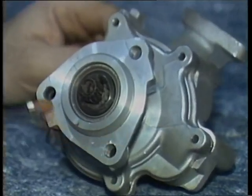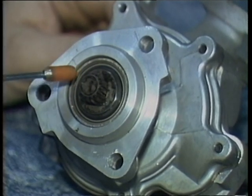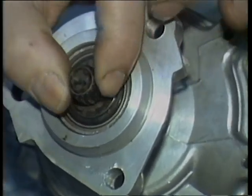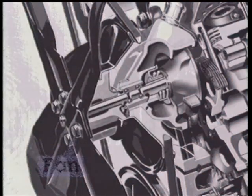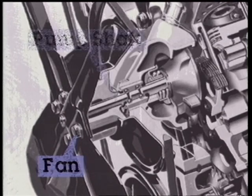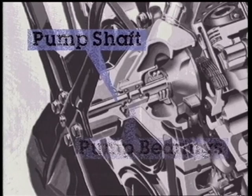This side-mounted water pump has a unique drive arrangement. It is a splined shaft that meshes into the rear of the drive gear. The timing chain on the engine, not a rubber belt, powers this pump. Here you can see how a fan typically bolts to the front of the water pump. The pump shaft is made of hardened steel so that it can support moving parts without excessive wear.